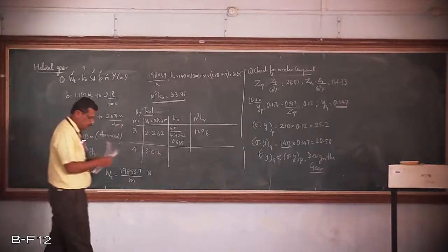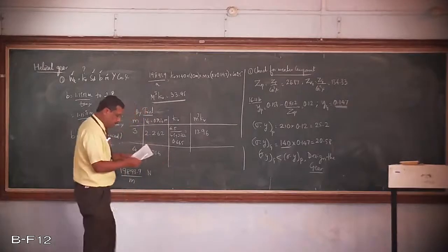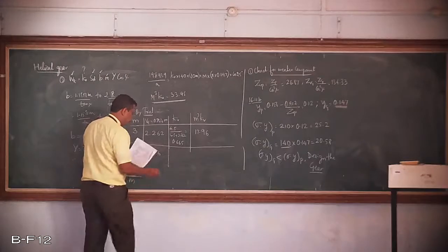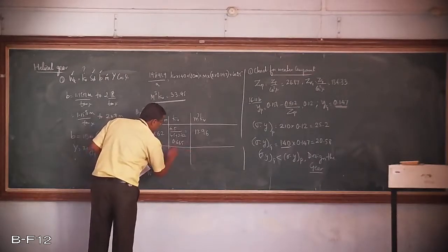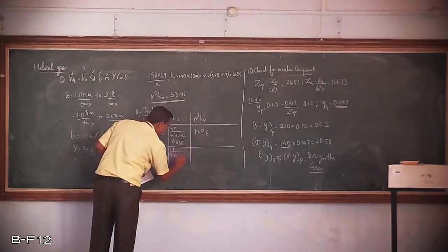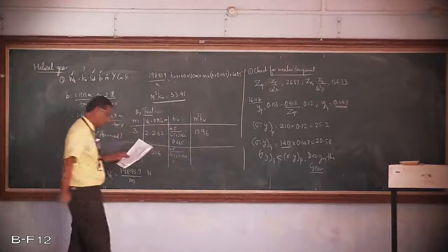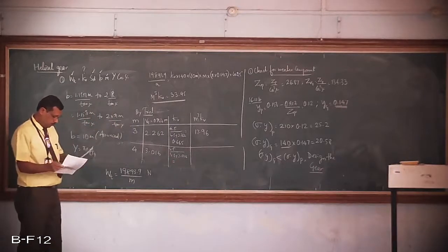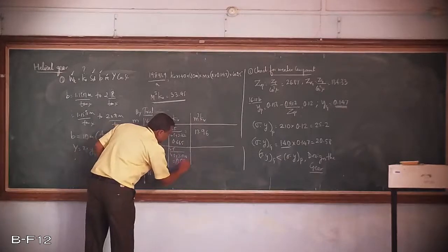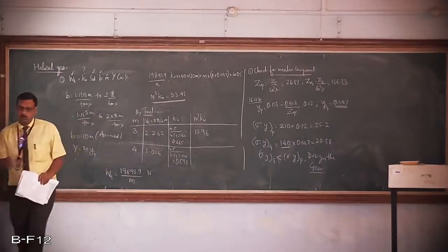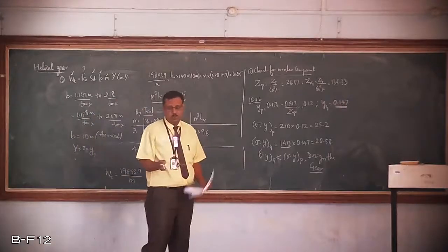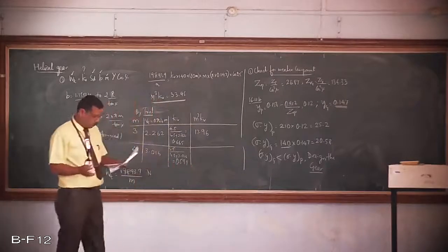Now again compare. It is still less than 5 meters per second, so you can make use of kV as 4.5 divided by 4.5 plus 3.016. That gives a value of 0.599, or you can round it off to 0.6. Because of rounding errors, the answers may vary slightly, however the variation will not be too much.